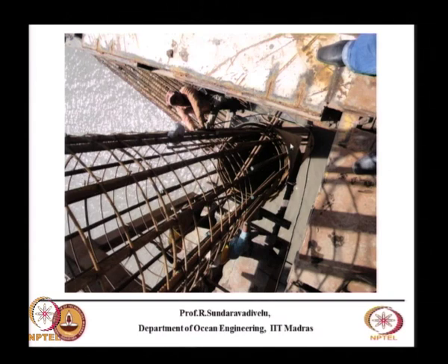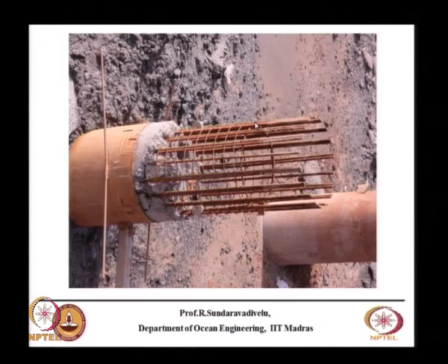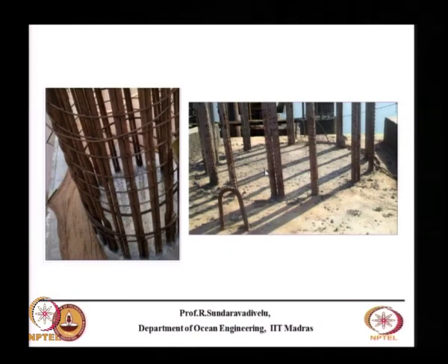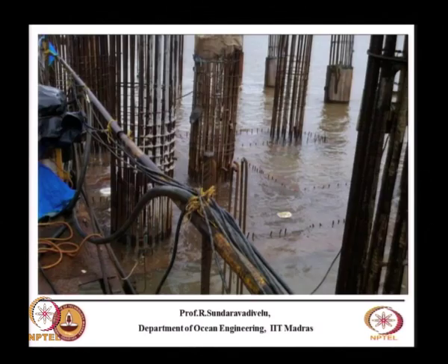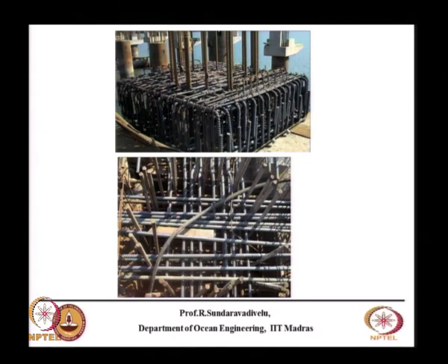They are transporting by barges and lowering it into the pile. This is the cover block, this is the liner already driven there, and this is concreted up to this. The top concrete will generally not be good, so they remove some top concrete here. You have to provide these lap bars so that you can connect it to the beam section. So, this is the reinforcement detail for the pile cap.